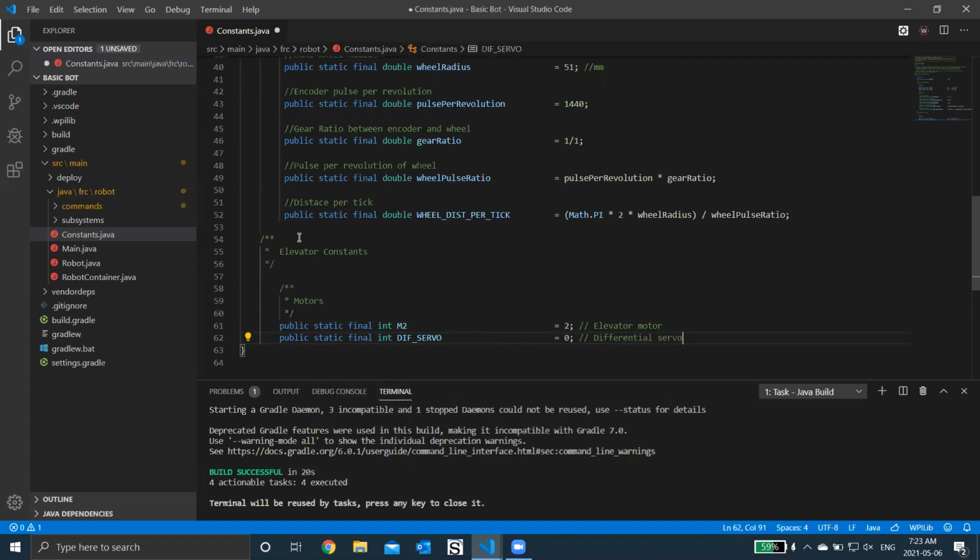The servo on the elevator to control the differential of the clock is plugged into port 12 on the VMX. However, this corresponds to PWM 0. So I must use 0 and not 12. If I use 12, that's a different PWM location on the VMX.